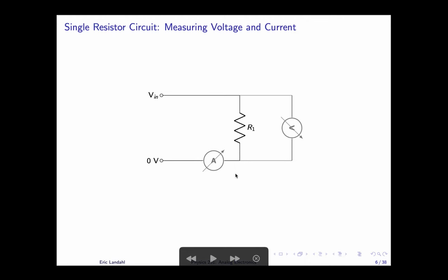And resistors that we grab, that have color codes, sorted into bins and boxes, we usually presume those are very, very good resistors. That is, they obey Ohm's Law very, very well. So actually measuring the voltage would be sufficient, because when you place that resistor across, you can calculate the current that's running through it from Ohm's Law.